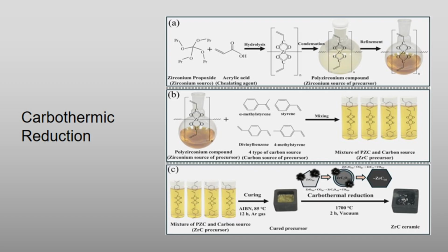during baking. Carbothermic reduction. The raw silica and carbon are heated together in an electric arc furnace at temperatures exceeding 1900 degrees Celsius to yield elemental metallurgical grade silicon. This demonstrates the phase transformations, microstructural effects, and atomic configurations during this high temperature process.